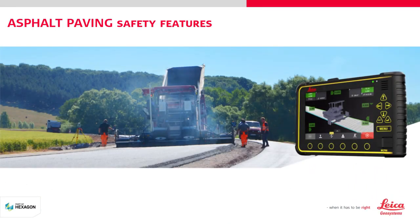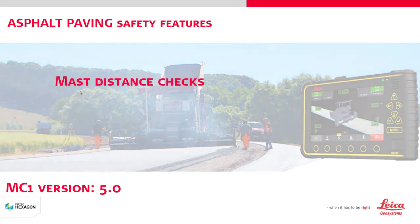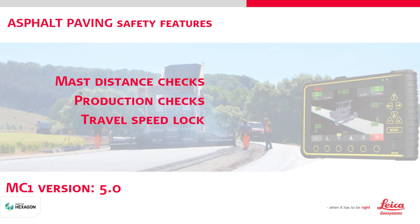In this tutorial, you will learn how to use safety features on your MC1 asphalt paving solution. These features will help you deliver high-quality paving. MC1 provides 4 safety features: mast distance checks, production checks, travel speed lock, and sensor timeout action.